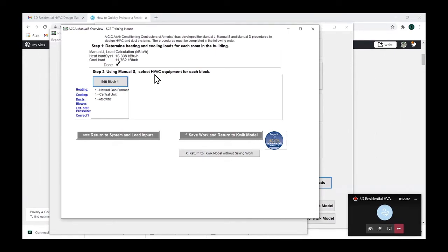A lot of people don't realize this, but if you undersize your ducts and you reduce your airflow across your evaporator coil, your cooling capacity goes down. Okay, and so your airflow, whether it's really high or really low, will change the amount of cooling capacity that your air conditioner will give you. And you're trying to size this to meet your load. And if you're close, undersizing your ducts may make your air conditioner too small, okay?